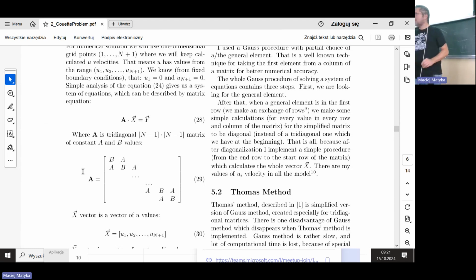If you increase the Reynolds number heavily, like to 10,000, okay? This will be so fast that it will go with a velocity 1,000 times faster. What happens in Couette flow? You will see turbulence. So you will see pressure differences. You will see vortices in the flow. That's true. But here, to solve it, we need to assume it. And this gives us also a solution.